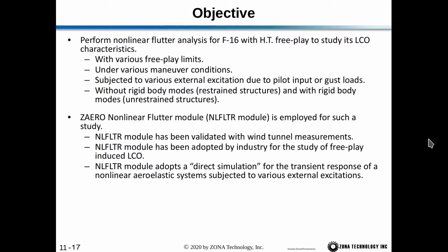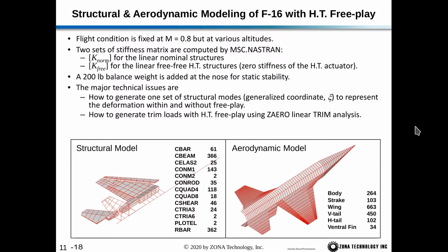The ZAERO Nonlinear Flutter module is employed for this study. And as we said, the Nonlinear Flutter module has been validated with wind tunnel measurements, as we saw in the last section. The Nonlinear Flutter module has been adopted by industry for the study of Freeplay-induced LCO. And the Nonlinear Flutter module adopts a direct simulation for the transient response of a nonlinear aeroelastic system subjected to various external excitations.